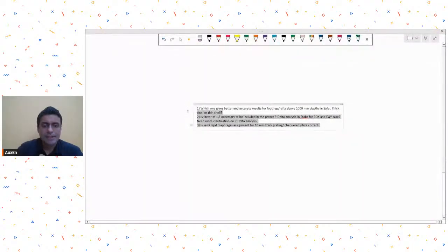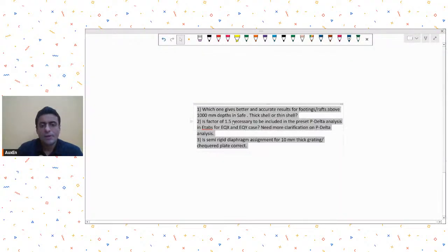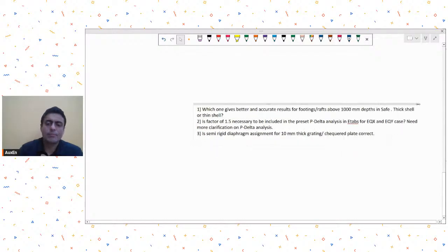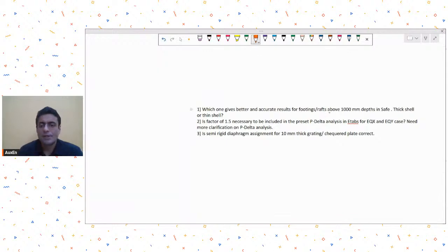Okay, so he is saying which one gives better and accurate results for footings or rafts above 1000 mm depths in SAFE, thick or thin shell. I have tried till 2 meters, 2.5 meters, and I had continued using the thin shell assignment. It gave me acceptable results.